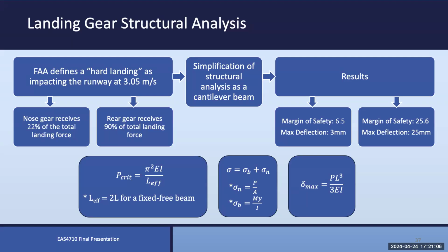So you've got fabric with 0-degree and 90-degree fibers, and fabric with plus-minus 45-degree fibers, so you've got different stiffnesses. You also have different moment of inertia contribution. A 0-degree fiber on the outer surface is going to be more effective in stiffening against bending than a 0-degree fiber at the neutral axis.